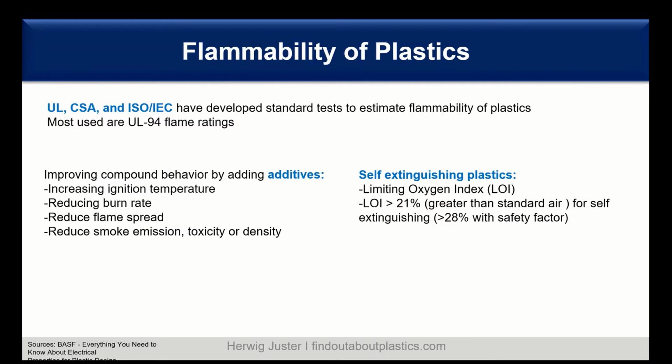And we also have self-extinguishing plastics, and this is measured with the limiting oxygen index, the LOI. Here's a rule of thumb: when you have an LOI bigger than 21%, so with a safety factor of up to 28%, when you take 28%, you have a self-extinguishing material.